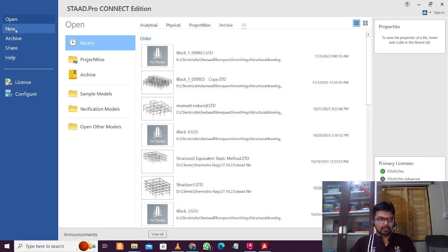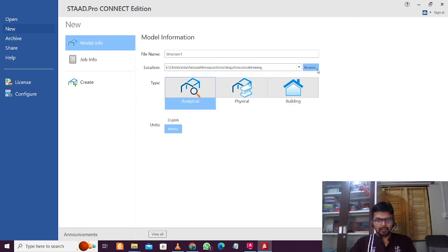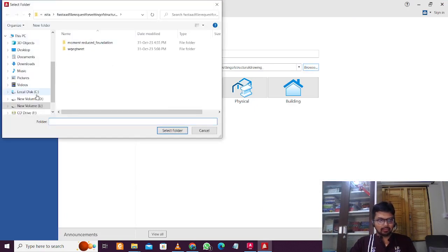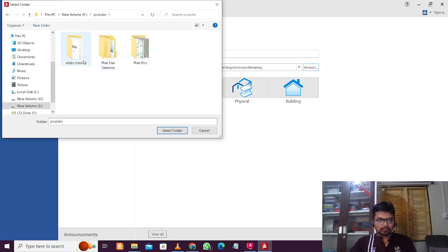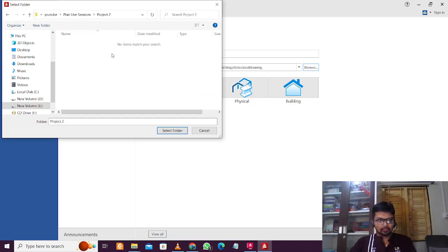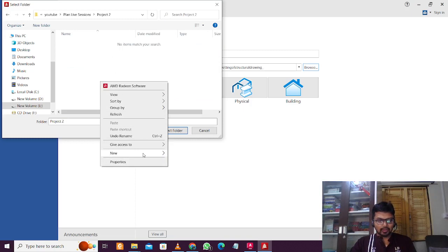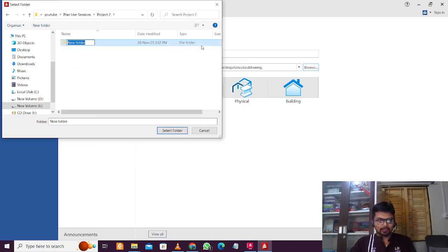STAAD has been opened. Click on new, and I'll browse to the location where I want this, and just name this STAAD file.